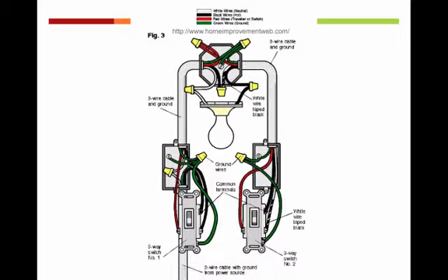Outlets, however, because you can plug things into them and the power can vary greatly, are usually 20 amp circuits. They usually can handle a greater amount of current. However, they also require a little bit larger gauge wire so that they don't heat up as quickly, and usually use what they call a 12 gauge or a 12-2 wire. So this would be a 14-2 wire, and what we see happening is that it's feeding up into this box a white wire, which we can see coming up, a black wire, which is going to go right straight to this light switch, and a green wire.